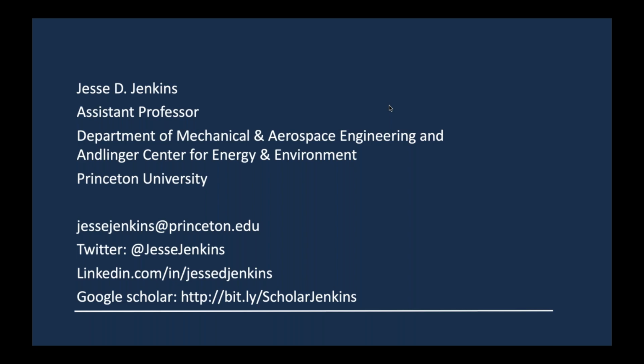But in general, pumped hydro is very limited by siting constraints. And so, where it's cost effective, it can play a role. It generally is not a long duration storage option. There are some pumped hydro facilities that have several weeks or months of storage, but those tend to be constrained by irrigation needs that also use the same reservoir for seasonal irrigation. And so they're not fully flexible for power sector needs.